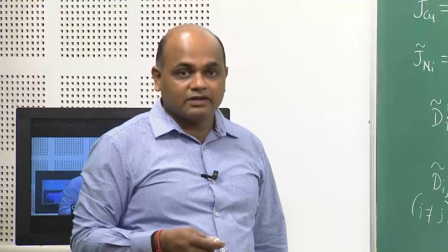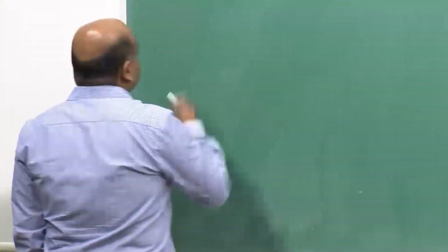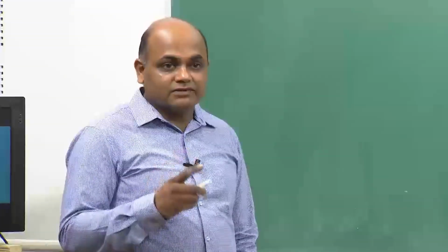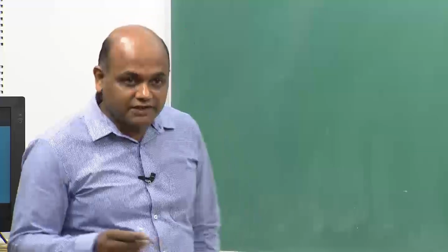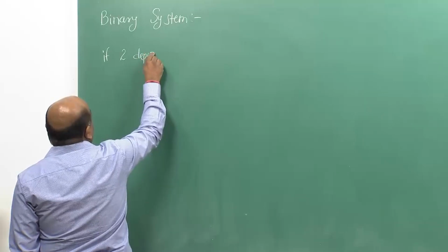Okay. Now, let us try to apply Onsager's formalism of Fick's law to a binary system. Binary means 2 components, right. So, we have only one independent interdiffusion flux, one independent concentration gradient. So, if we treat 2 as dependent,